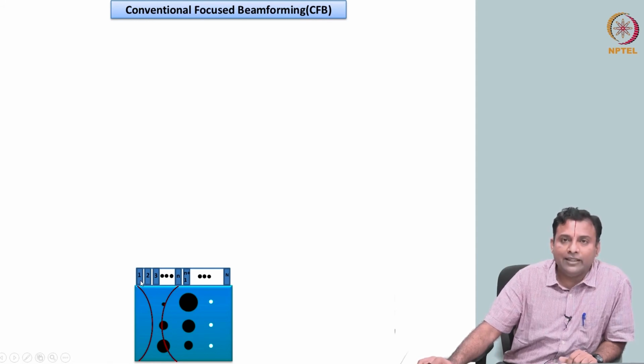Elements are exactly the time delay calculation that you did for your phased array, just that the theta is 0 here, right? So you can excite with the delay value that is computed so that you get focusing at the center of this aperture, what we call the active aperture. What happens when you send it like this?